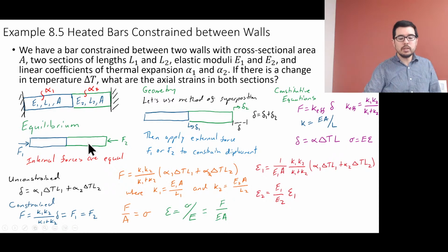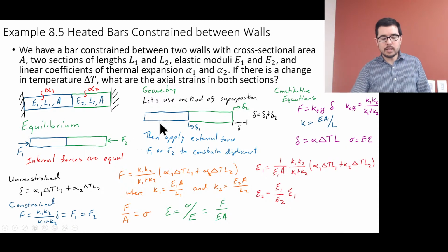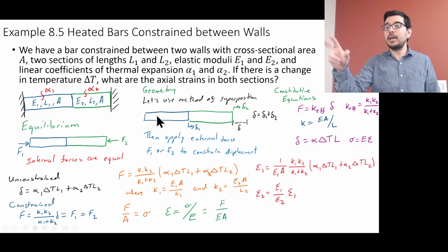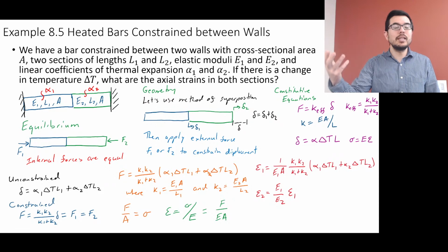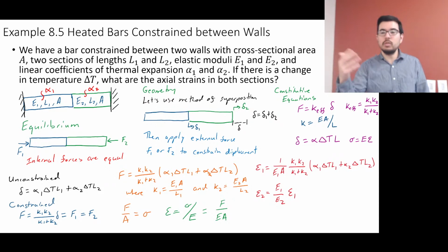And springs in series, or bars, this is like saying, if I take a cut in the bar and I have a force on the left side, then there's no other loads. We just did this whole thing with axial loading, and we said we had to add an external load for equilibrium to happen. But if there's no external load, then we're just going to have the internal force equal to the external force acting on the bar.